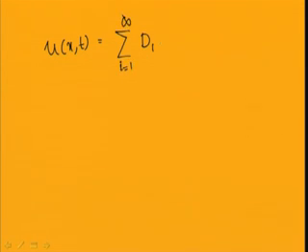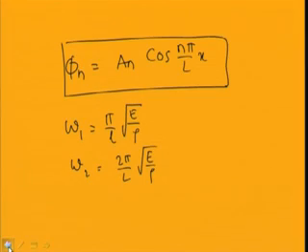So, the general vibration or the free vibration response of the system, you can write u x t will be equal to summation, like in the previous case of string, I can write this as summation of d1 i cos omega i t plus d2 i sin omega i t, i equal to 1 to infinity, into, so in this case it becomes cos.